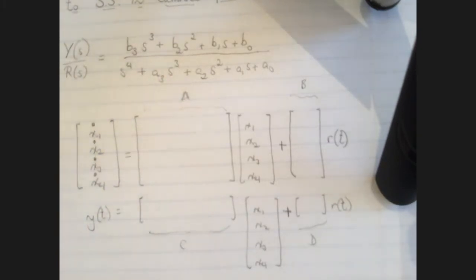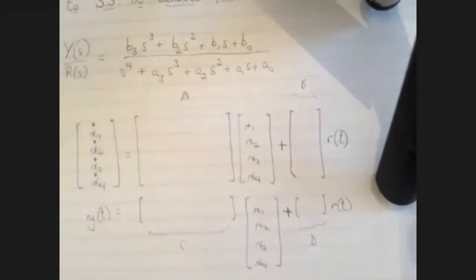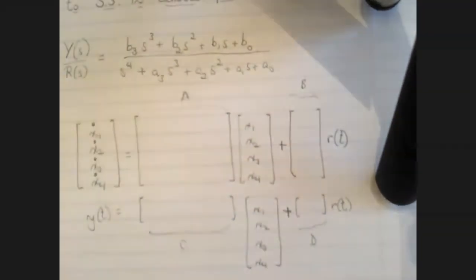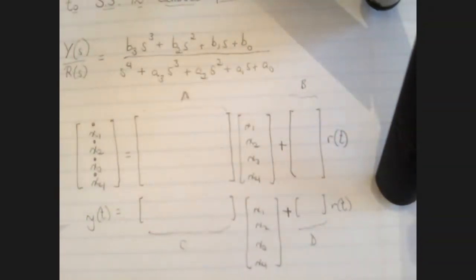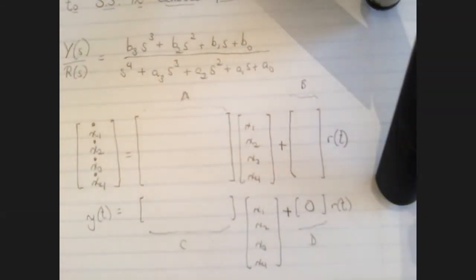It turns out that there's a pretty structured way to do this, and it's a bit of a recipe. The first thing is matrices B and D are actually going to be the easiest ones. Actually the easiest one is D for the canonical form. This is the only one we can pull off systematically, this canonical form. And the D matrix is always 0. So this one always goes away. There's going to be nothing at all there.